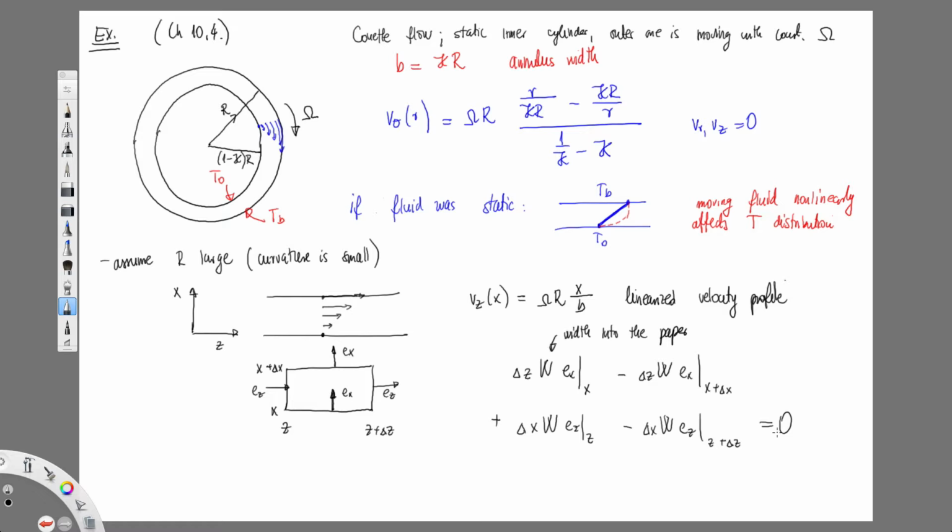Again, because we neglect outside forces. We neglected gravity in our solution for velocity as well. So that's consistent. And no production. So no reactions or anything that could produce heat. So we neglect work of the outside forces and there is no production. So this is our balance.